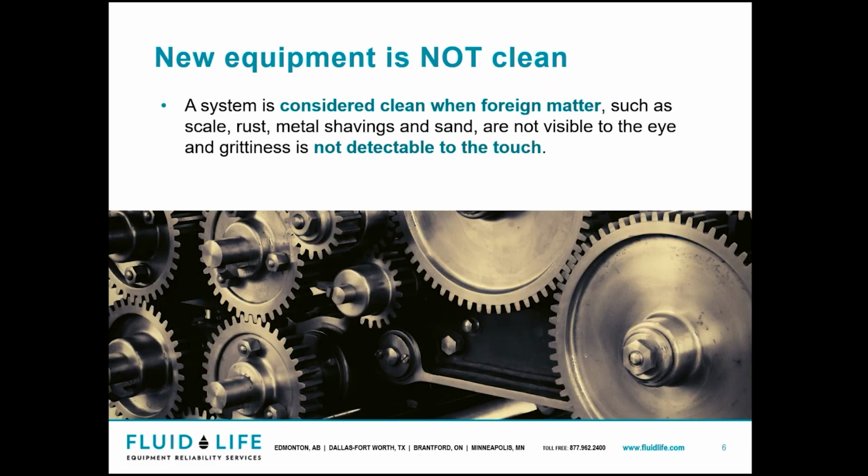Now, when I was talking about my colleague having a new vehicle and the oil appearing clean, well, technically, according to API standards, if you can't feel or see dirt or particles, it's considered clean. To give you an idea how big that would actually be, take a piece of paper and look at the cross section of it. That's 40 microns, the smallest that we can see.